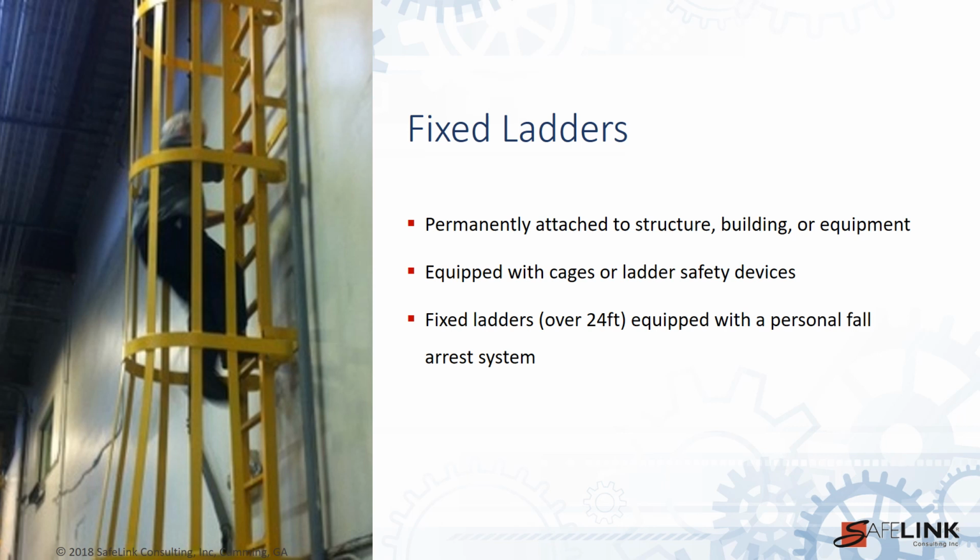Fixed ladder safety. A fixed ladder is one that is permanently attached to a structure, building, or equipment. It is normally equipped with cages or other ladder safety devices. Fixed ladders over 24 feet must be equipped with a personal fall arrest system.